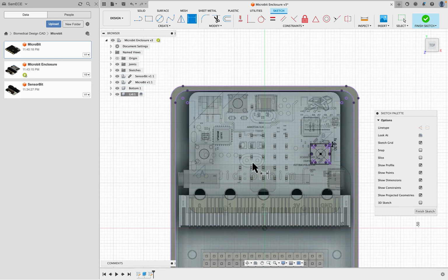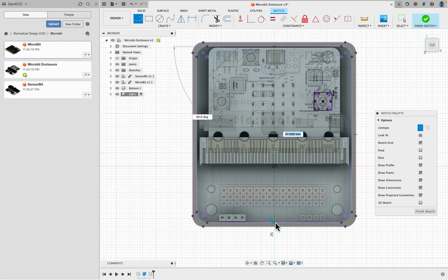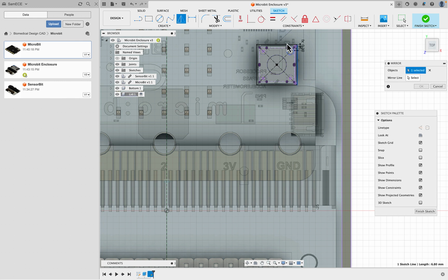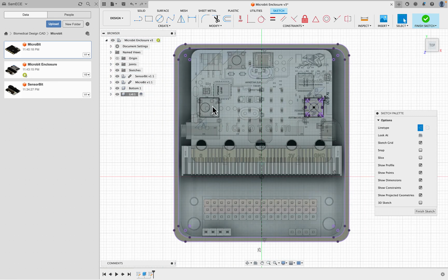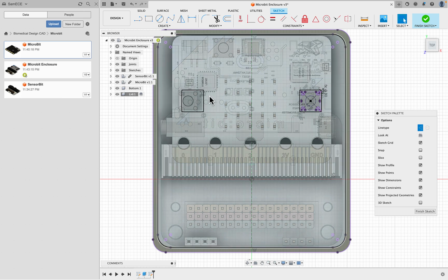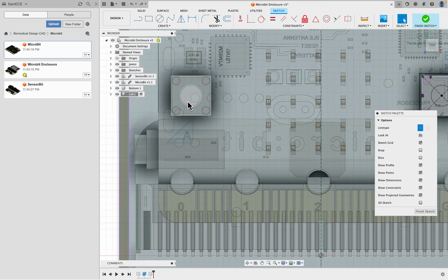I could do the same on the opposite side, but once more it's symmetric, so I'll just create an L construction line going through the entire center of my lid, and then I can create a mirror of the outer surfaces or lines of my rectangle using the center line as an offset. And, wow, would you notice that it's not symmetric? So there you go. Bad idea. I'll just hit Control C. So we actually need to project this one and do it all over again.